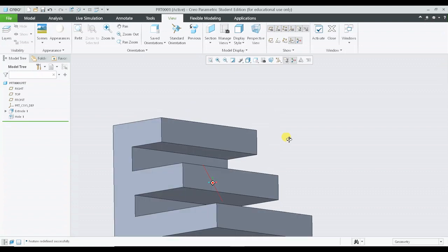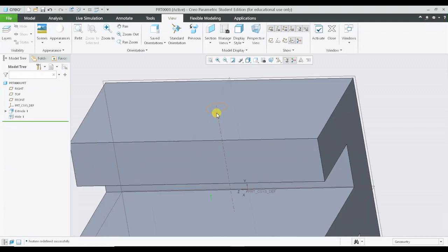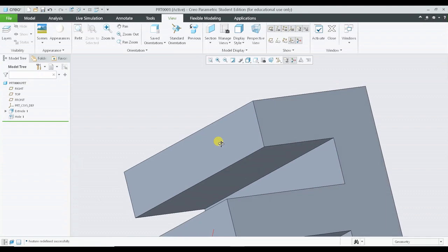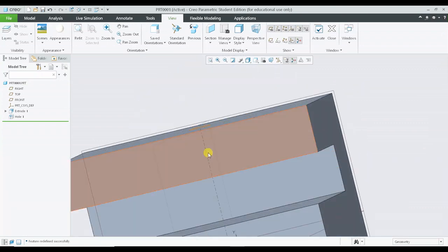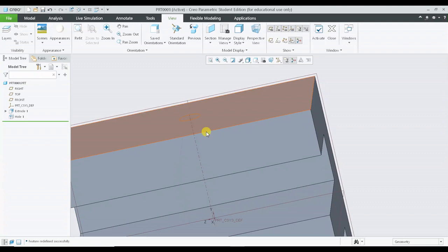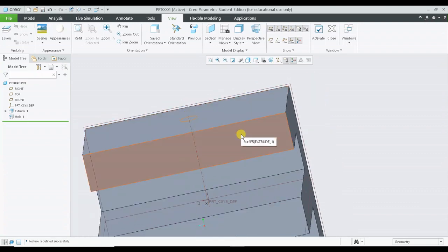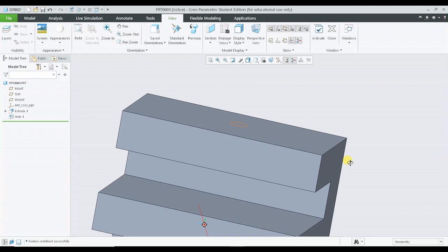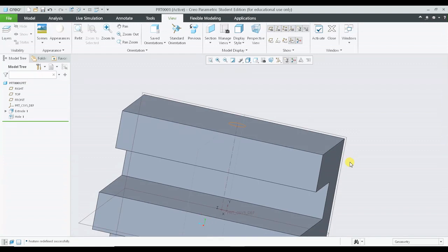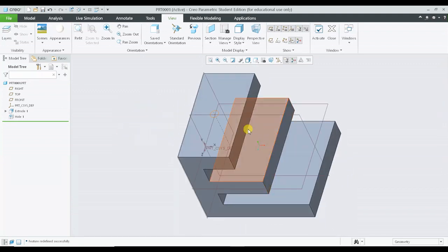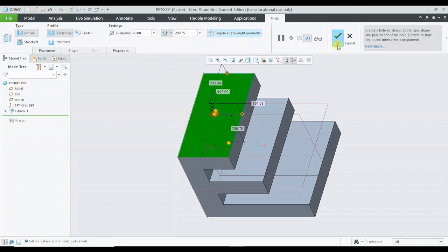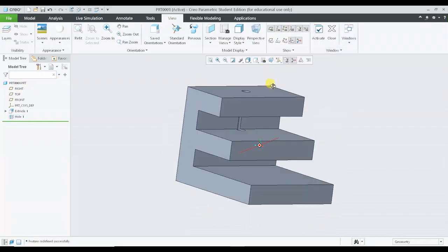It basically eliminates the hole, but a hole is present over there. It is not visibly seen on the screen. The feature is removed. We can only see the axis and the circular sketch. So this indicates that a hole is present over here. And this will basically not get involved in the graphical memory, or this will not delay your system or lag your system to work. And you can also have a feature ready with this. If you want to visibly see it, we can simply go back to hole, edit definition, and we can turn off the feature, press OK. You have the feature with you.